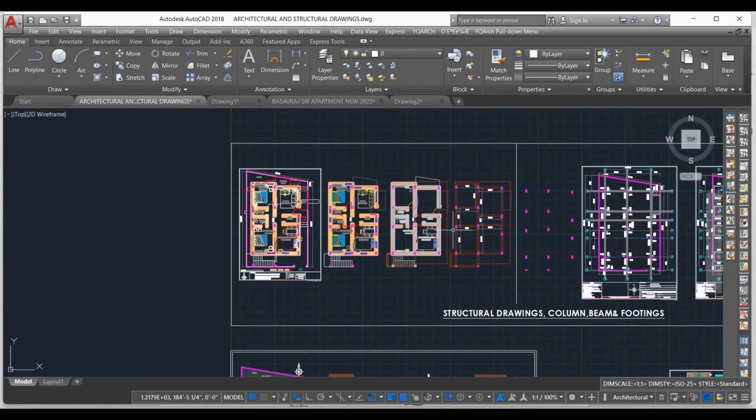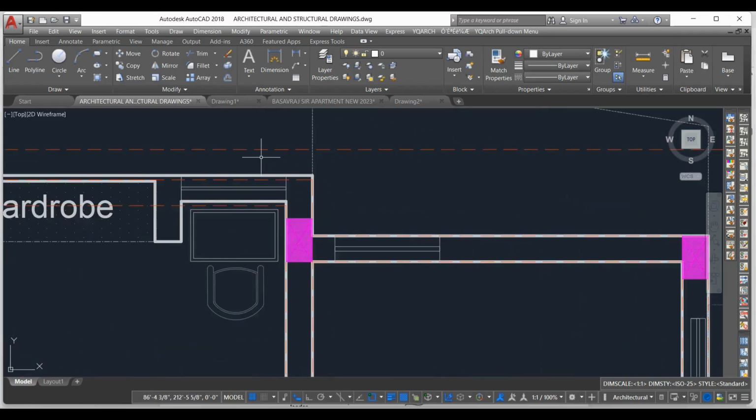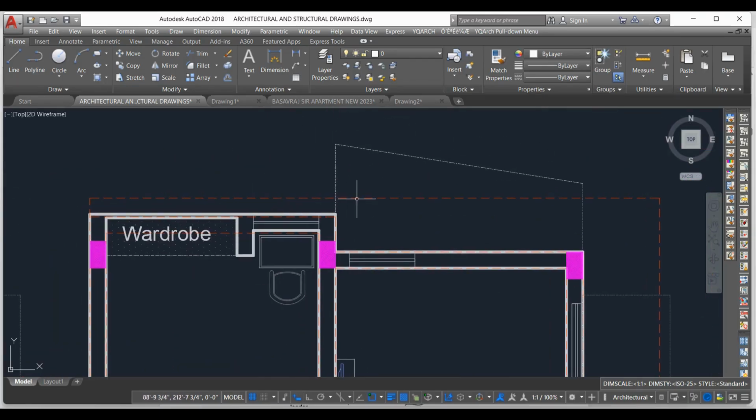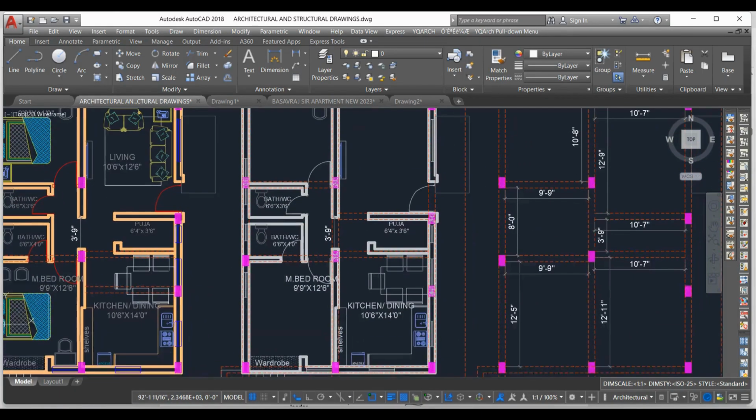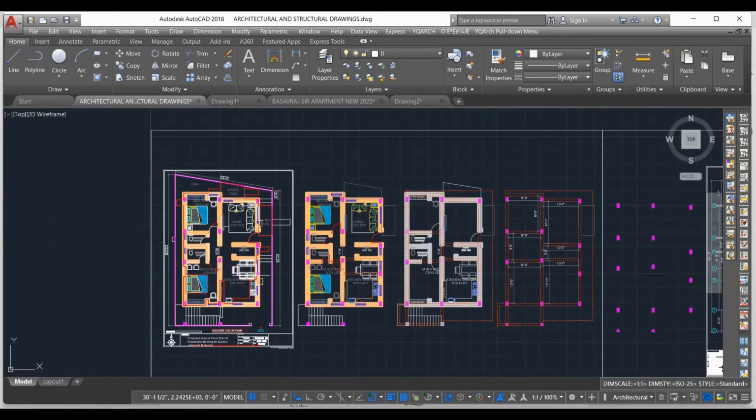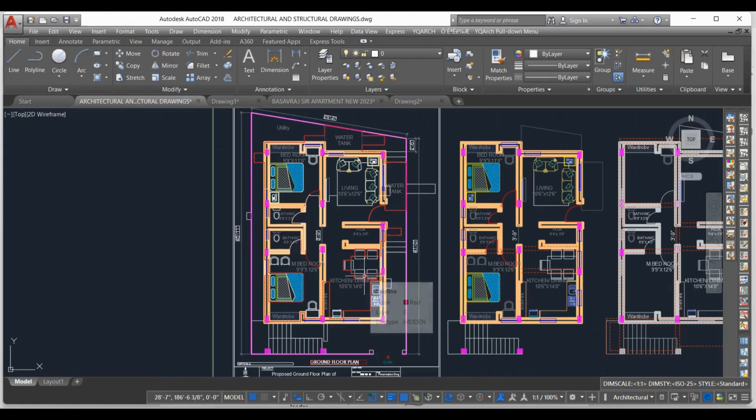Next is slab projection line. This one we call a projection line. The portion which is not visible at that particular level, we call a projection line, slab projection line or beam line, like this. So we learned till now what the different types of lines are, what thickness we have to give, and the implementation of it. I already presented how we use it. Now in the next part, I'm showing you how we have to prepare all these lines. With an example I will teach you.